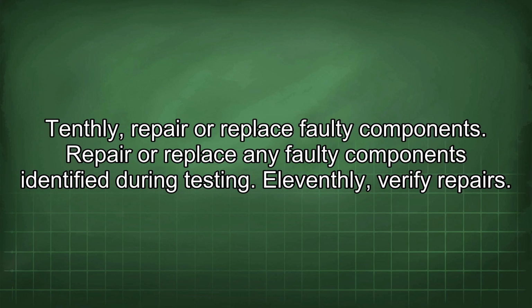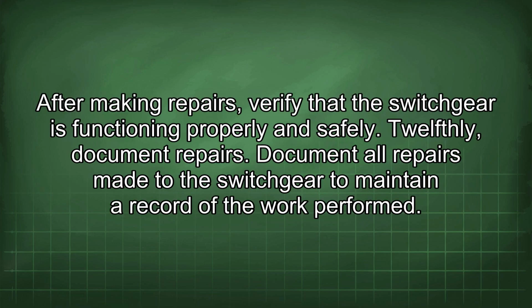Tenthly, repair or replace faulty components. Repair or replace any faulty components identified during testing. Eleventhly, verify repairs. After making repairs, verify that the switchgear is functioning properly and safely. Twelfthly, document repairs. Document all repairs made to the switchgear to maintain a record of the work performed.